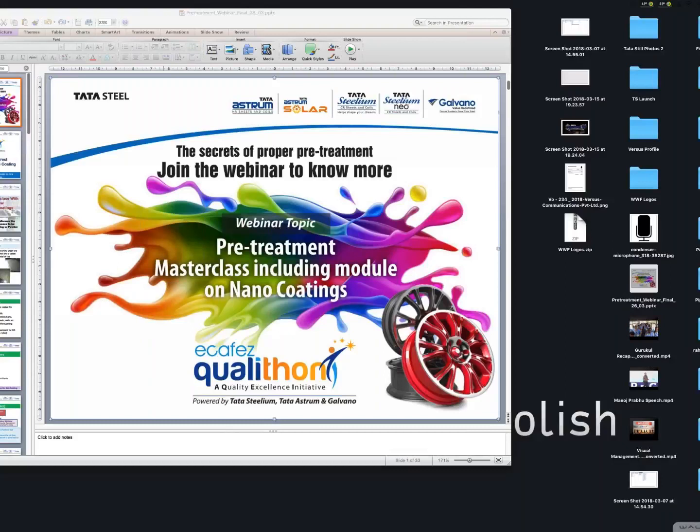One, we are not heating it up, so some of the cost goes down. Then it's a 9-tank process, with no activation, no passivation, so that cost you can reduce with nano coating. Then the ETP cost and disposal cost of phosphate sludge, that cost also you can take out.